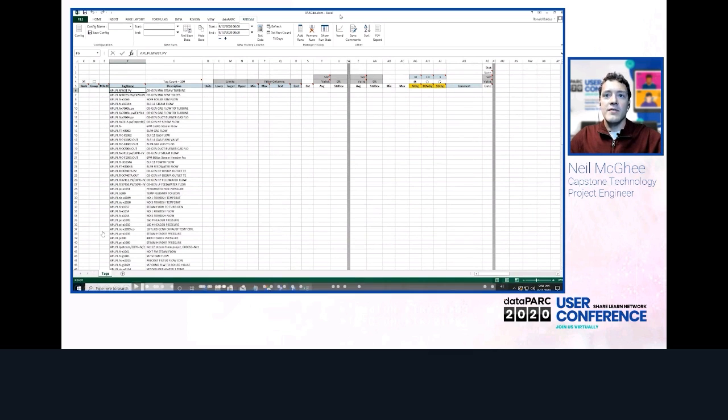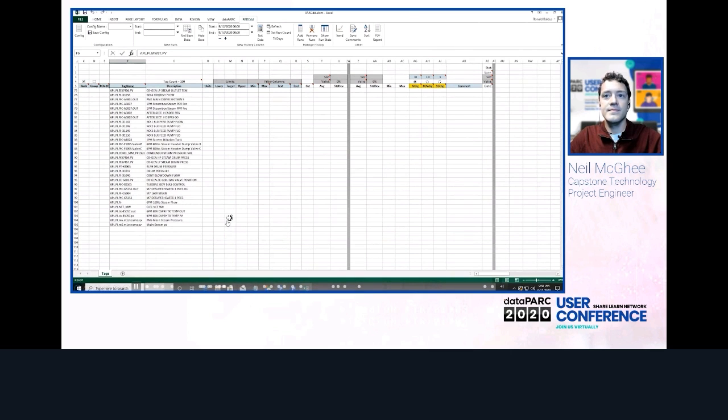The tags we are looking for to use for our filter are some Steam flows that indicate which machines are running. We will set a minimum Steam flow that indicates that a process is not acting under normal conditions. We add an X to the exclude column so that the data will be filtered from all tags, not just these two specific tags. This is the same format as the DataPark normalized data sheets.